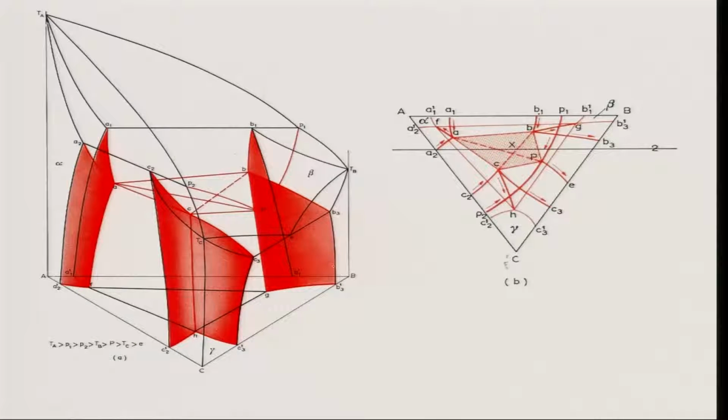On the other hand, BC forms a eutectic, which is represented by E. Now, these points which I have drawn inside A, B, C and P, correct. These points are coming basically from the solid solubility limits A1 and A2 for the AC binary and the AB binary, right.